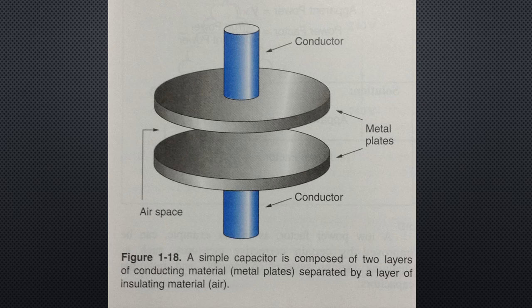In an AC circuit, the voltage is constantly changing direction. The current is initially in one direction, charging the capacitor, and then in the opposite direction, discharging the capacitor. Therefore, current continues to flow, alternating back and forth, with the capacitor plates charging and discharging.